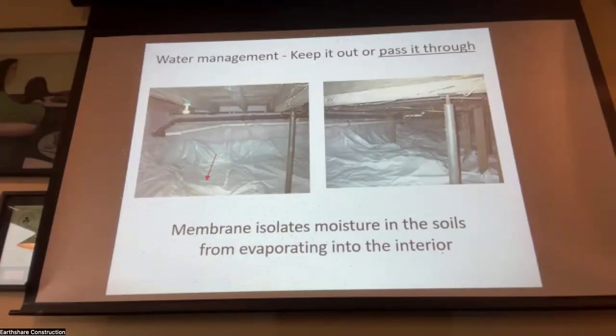You run into issues with the plastic running behind the foam and not getting adhesion to the foundation. That's why we pick Too Tough, because the foam will bond to it. Yeah. If you use plain old poly, it won't stick. Or if you crawl around on there and pull the plastic at all, it'll delaminate, and then you lose your seal. It's a great question. You want to pick a product that the foam will bond to, and if you're not sure, take a kit and spray it on some of the plastic you're thinking about using, and make sure it doesn't debond.